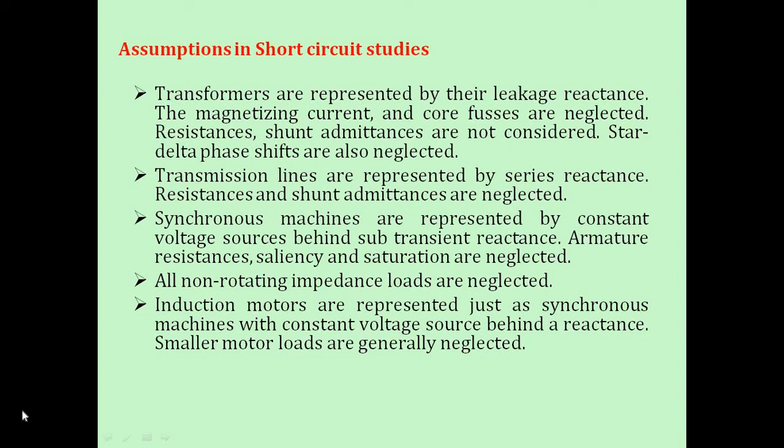Synchronous machines are represented by constant voltage sources behind subtransient reactance. Armature resistance, saliency and saturation are neglected. All non-rotating impedance loads are neglected. Induction motors are represented just like synchronous machines, with a constant voltage source behind a reactance. Synchronous motor loads are generally neglected.